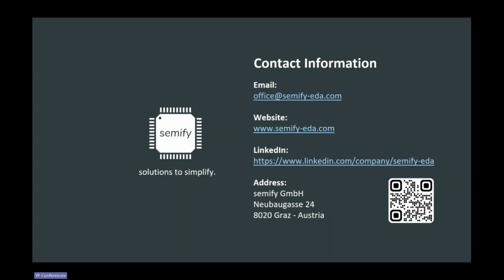Is the code for the model synthesizable SV, or is it a mix of class SV and real SV? Good question. It's right now pure SystemVerilog, and there's just one parameter to make it synthesizable or not. All this parameter really does is select a generate block, whether it's a 2-flop synchronizer or the actual model. So it's synthesizable, no UVM required, pure SystemVerilog.